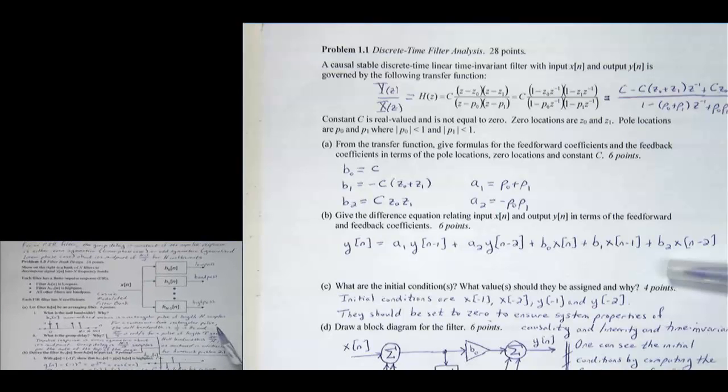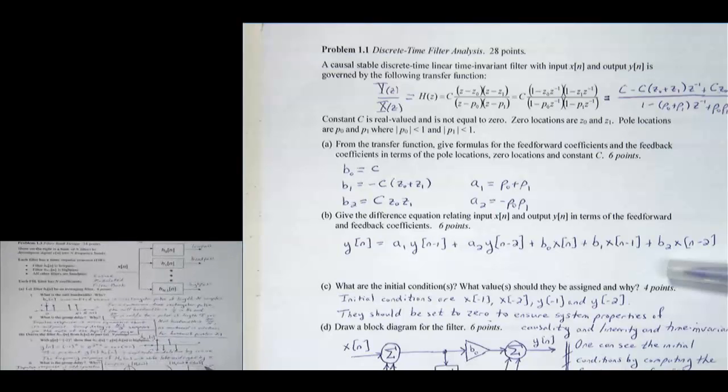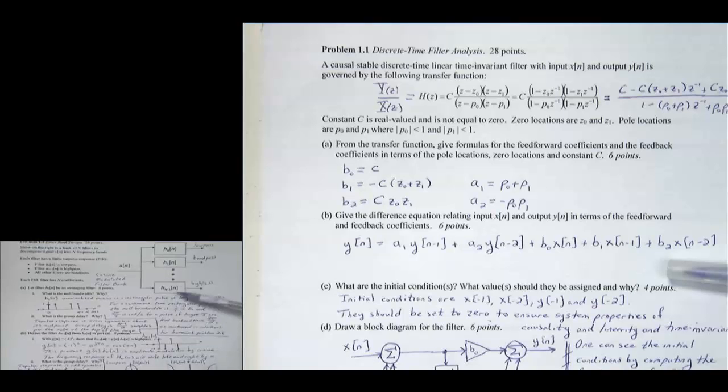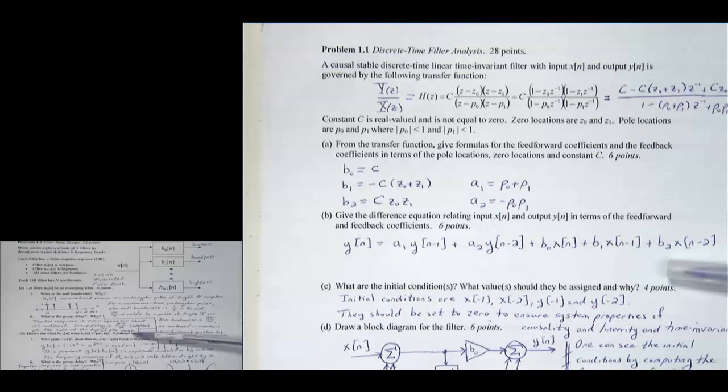All right, now it's going to get tougher, much tougher. In part B, I'm asking you to derive the high-pass filter. And this is a really hard problem. I said derive this high-pass filter from the low-pass prototype h0[n], and I tell you how to do it. So I give you this g[n], which alternates 1, minus 1, 1, minus 1. And it could be two-sided.